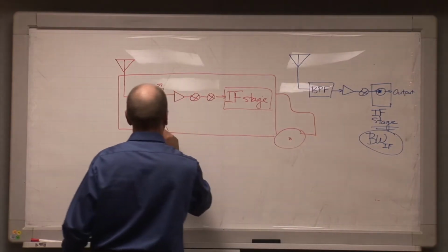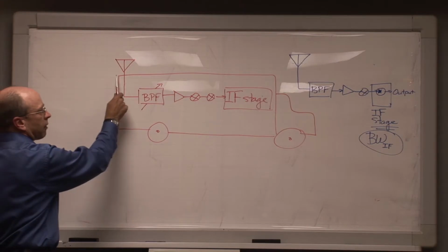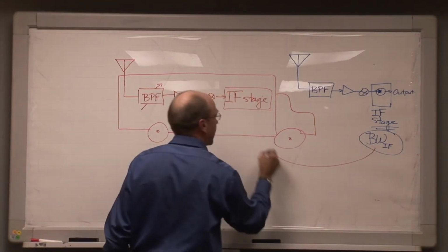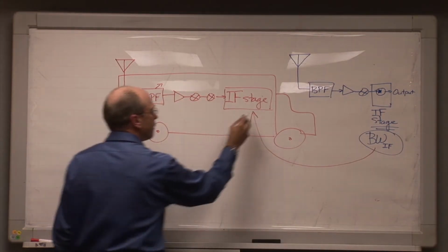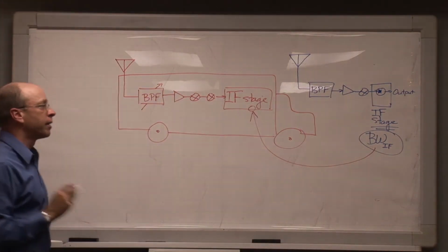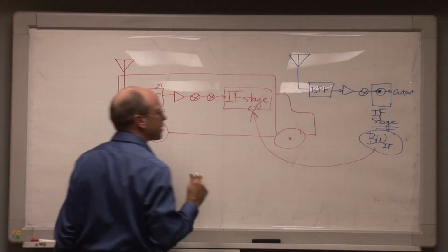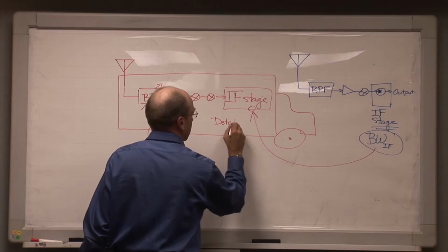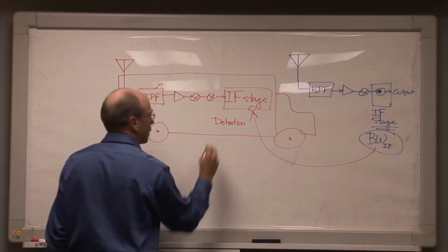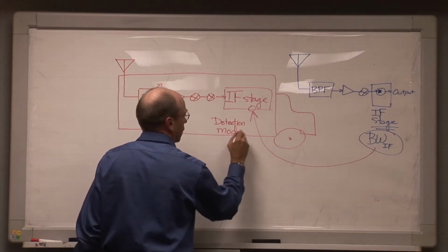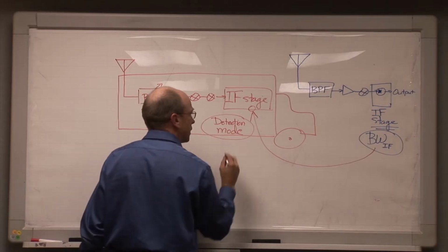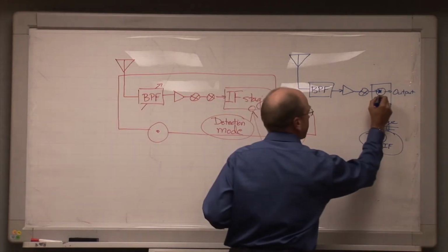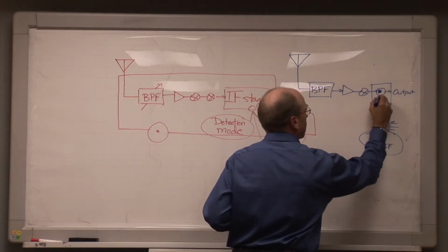Okay, there's our measurement system on wheels. What we're trying to do here is replicate with our measurement system what's happening with this receiver. So it's important that this IF bandwidth, if at all possible, be used for our measurements so that we're now seeing the spectrum through the same bandwidth as they're using. We also try to set our detection mode, and we've talked plenty about detection modes in this series. We'll set our detection mode to look the same as their detection mode over here.